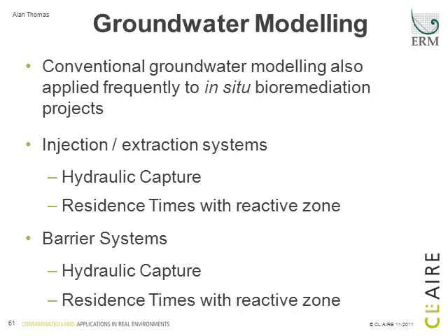Conventional groundwater modelling is also frequently applied to in-situ bioremediation projects, particularly where we're looking at injection or extraction systems, where you may be wanting to demonstrate the likely hydraulic capture or estimate the residence time within the reactive zone. Equally for barrier systems, again you may want to look at hydraulic capture, and if for example it's a permeable reactive barrier, you may want to look at residence times within the reactive zone.